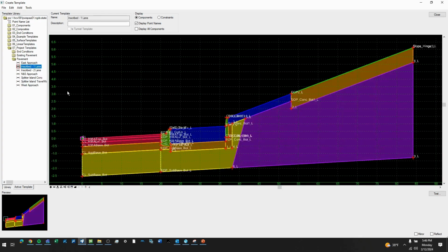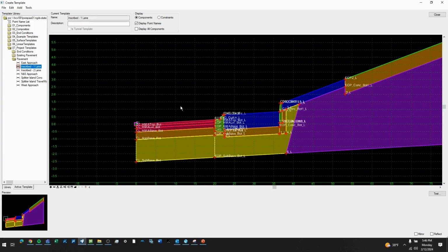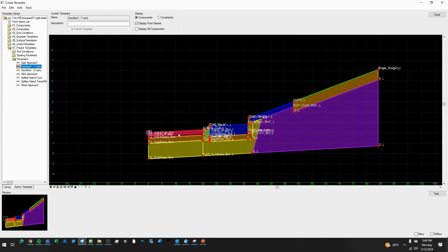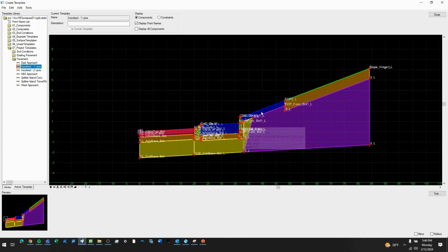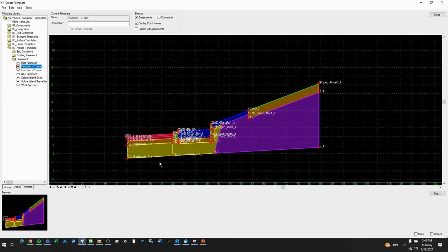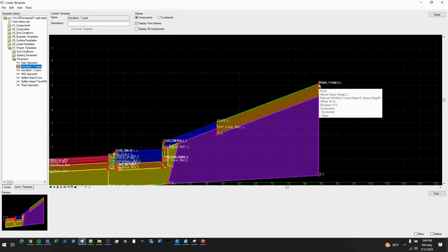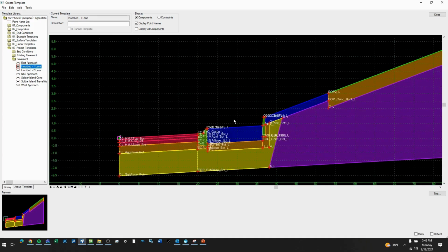So these inscribed, I have to have 2 of them. Again, a 2-lane and a 1-lane. But this is basically building that center island. So this is your ICD, your travel way going around, and then you have your curb here. You have your truck apron, and then there's a little bit of pavement decoration that's going to go back. This has to do with sight distance and stuff like that, with some embankment and some different other things going on. And this is just a hinge line that roughly goes to the middle. You can change these depending on what your ICD is.